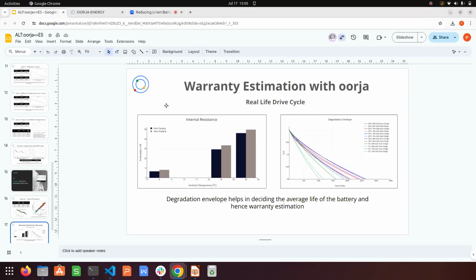Yeah. Right. So what happens is that when you are doing the dynamic cycling, often because you are operating at higher C rates, it is impossible to completely charge or discharge the cells, and hence you will never know the right estimates for the capacity at that moment.